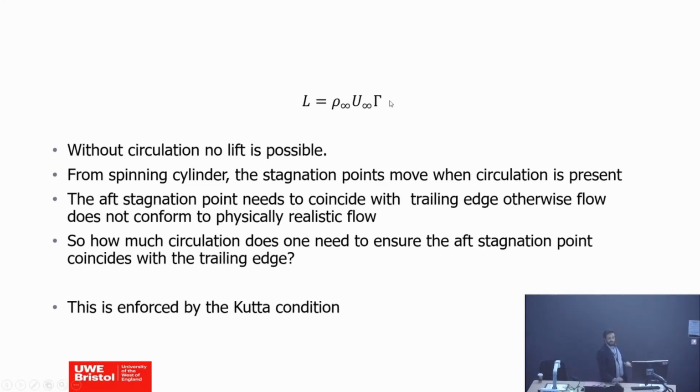Okay, now, I told you before that depending on the value of circulation, you get a different value of lift. And what we've seen for the circular cylinder, the lifting circular cylinder, is we get an infinite number of solutions depending on the value of circulation. It's exactly the same for airfoils. We can get an infinite number for a given condition of rho and u. If you just change the circulation, then you'll get a different lift.